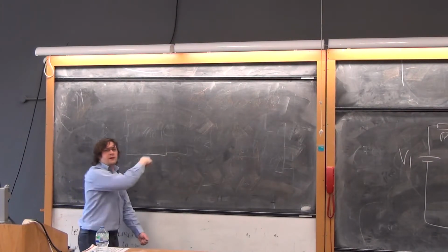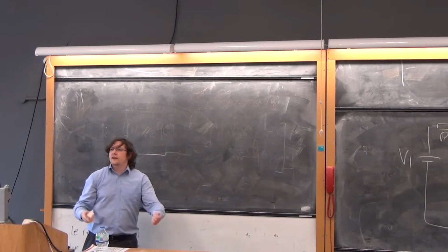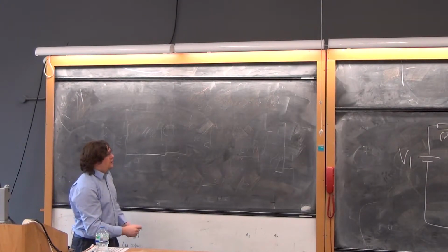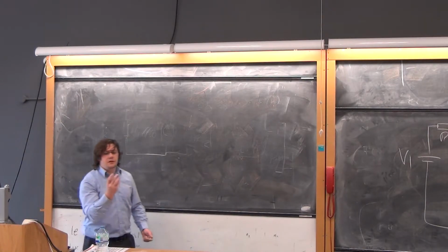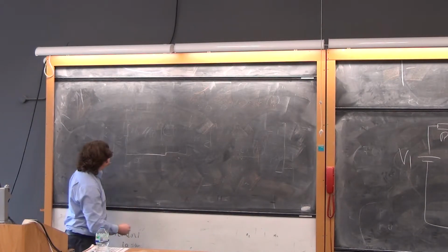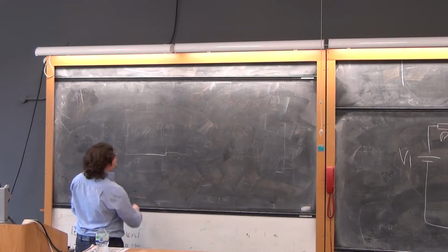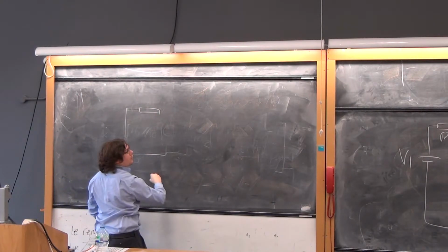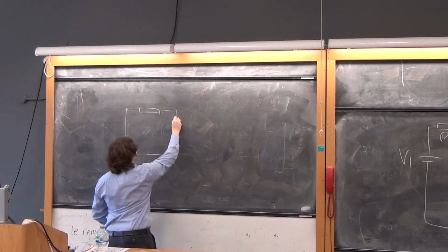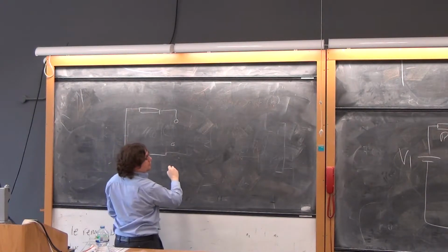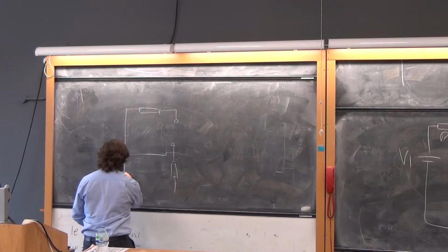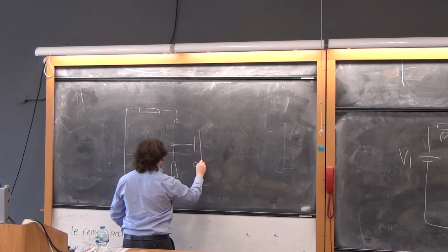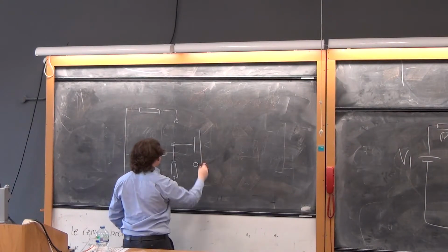So we will work out, well, I won't, but you would work out these answers and keep them. So we've worked out 2 answers so far, and now we have to worry about the diode because that's the only thing that's left to deal with. So to do the diode, we'd switch off the voltage source, and we'd switch off the current source, and we'd have 0.7 volts there.